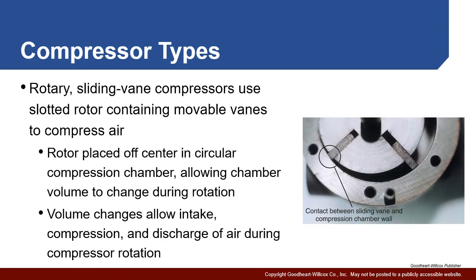One style of rotary compressors is a vane style or sliding vane style compressor. Take a look here on the right. Very similar to a vane style pump. It uses a rotor, in this case a slotted rotor with a set of vanes in here, and it rotates inside the housing, or what's known as the compression chamber in compressors.